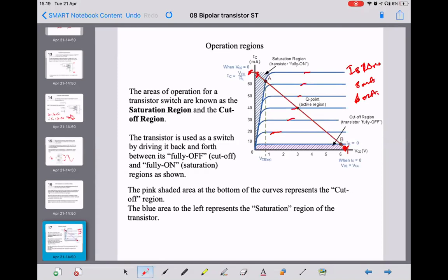So for different applications of IB, we can get different output curves from this transistor. But for the time being, we're interested in the fact that as a switch, we want to operate between the maximum IC current and 0 IC current: on up here, off down here.